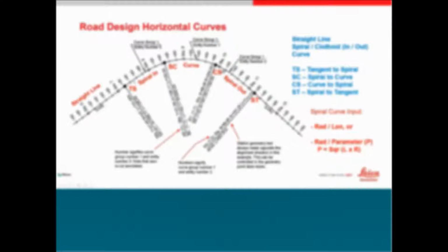When you come into a curve, normally you will need a smoothing of the curve. You cannot simply apply a curve that is too great, as that will cause danger to vehicles using the road, because they may skid. So you need a spiral curve that slowly changes from a straight line into the radius curve that you will apply.